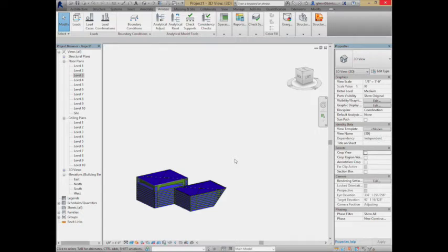It turns out it's often not too bad in the scheme. Your winner will almost always be somewhere in there. It'll be one of those two. It'll be something that's relatively low. And the only reason this sort of wins, it's not necessarily the most efficient shape. What happens is all this area down at the bottom is considered relatively inert. It's not losing any energy. It's not gaining any energy through it. So these long, low buildings often win.